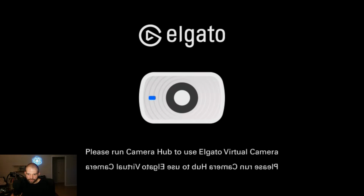So we'll try something else. Rather than 0.75 or 0.25, we'll go to 0.6. And rather than the Spider-Verse diffusion model, we'll go ahead and use the depth model so that we can not only rely on color, but we can also rely on depth. So that should keep us more true to the original geometry that's being put into the render. So as a final pass, we'll see how this looks and we'll call it here.